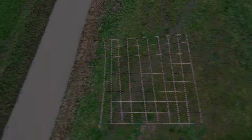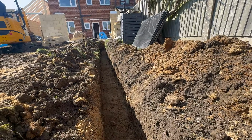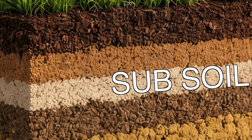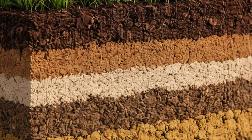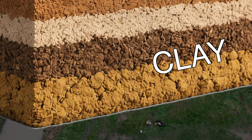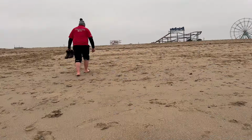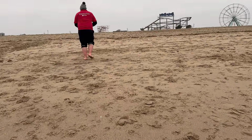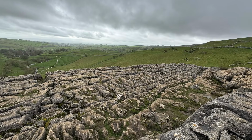At the surface, you usually have topsoil. This tends to hold moisture and often contains organic material and salts, which usually means lower resistivity. Below that, you'll often hit subsoil, which is more compact, holds less water, and already starts to increase resistivity. Then you may hit clay, which holds water extremely well and often gives very low resistivity values. Or you might hit sand or gravel, which drain water quickly, dry out easily, and push resistivity up dramatically. Go deeper again and you may reach chalk or rock, which can have very high resistivity, especially when dry.